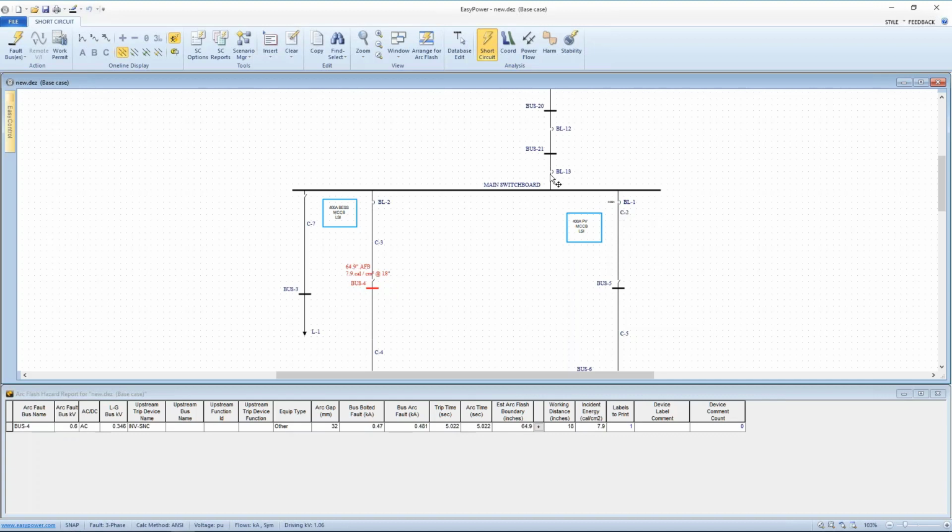So does the situation change if I take off my utility and my PV bank? Do we ever operate in this mode? Well, as I understand it, the answer is no. It's always a combination of the utility plus one or the other or both. So at this point, I'd want to create a scenario that allows me to open one breaker, evaluate arc flash and equipment duty, and open the other breaker and close the first one, and consider those three different combinations of breaker styles.